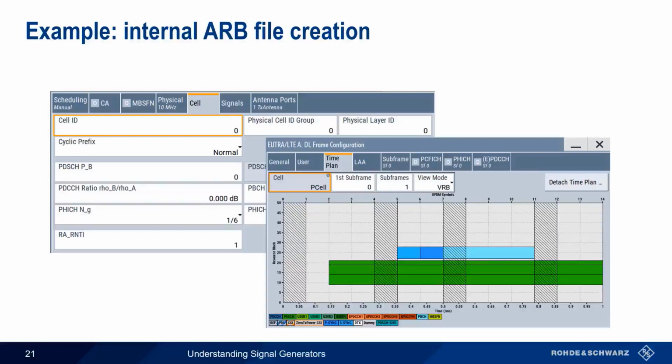Being able to perform this kind of signal configuration directly on the generator, as opposed to using external tools, greatly increases the ease and efficiency of defining vector modulated signals. The end result of this process is an arbitrary waveform that can be immediately generated by our instrument and/or saved for later use.